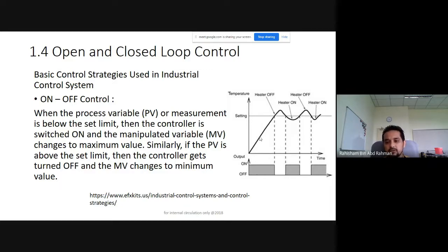But on the downside, this system is actually a waste. If you can see, there is overshoot and undershoot, overshoot, undershoot. So it's just a waste, and this discrepancy, this error, should be lower. If we have a mechanism that detects when it reaches this point and starts to turn off the boiler, we want to control the flame, make it smaller, bigger.